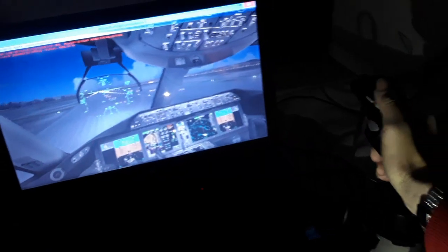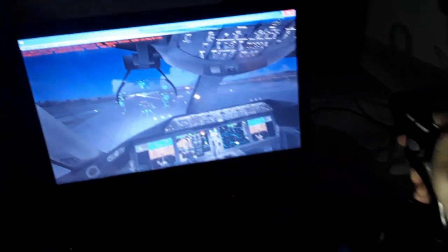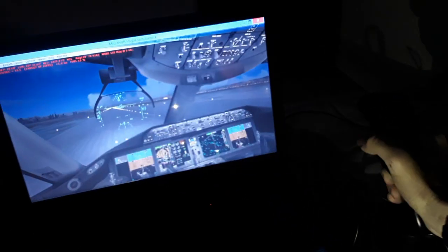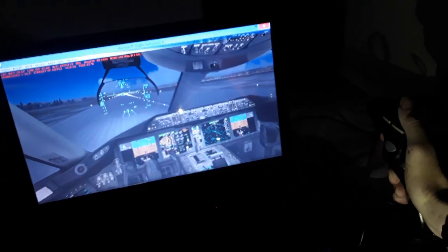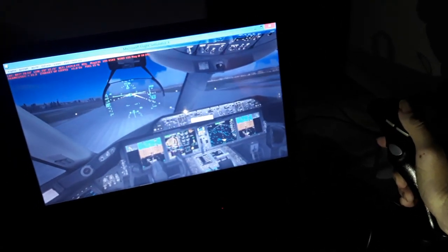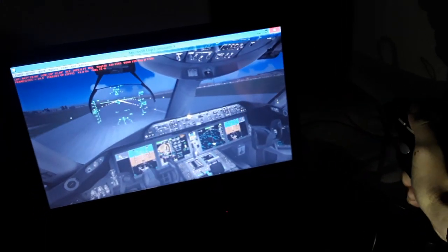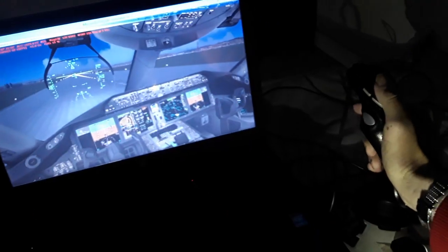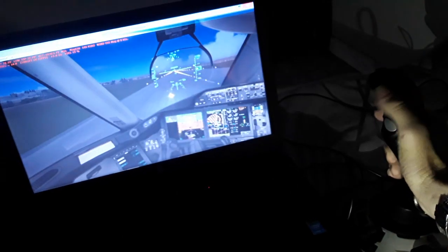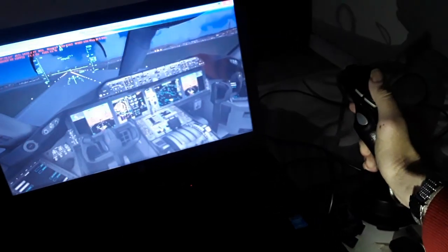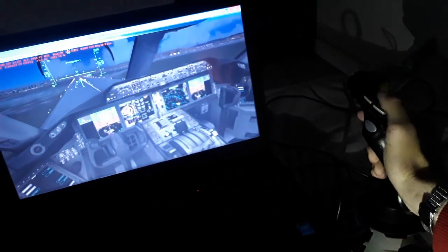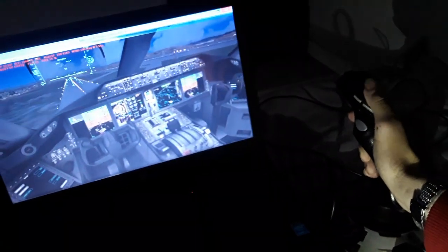And align with the rudder pedals. So we have the takeoff, go around here, thrust, full thrust. So we have 80 knots, 100, 110, V1, we rotate over here. So we rotate like 9 degrees slightly, as you can see. And we climb, we have the takeoff